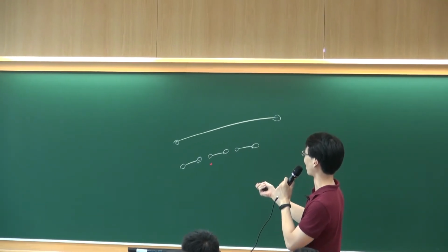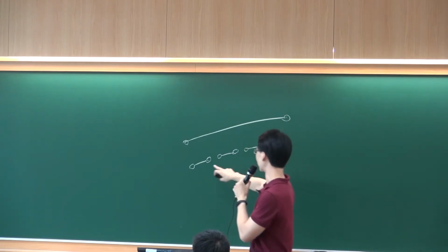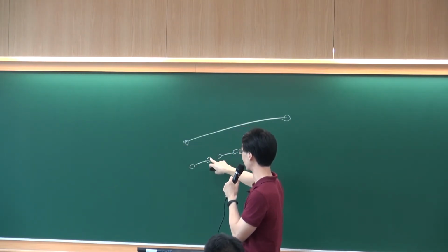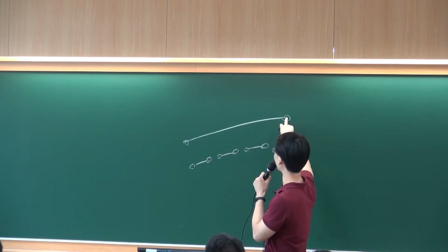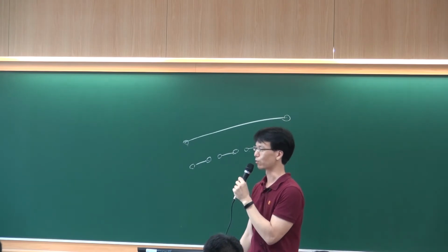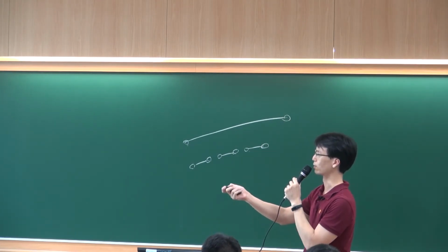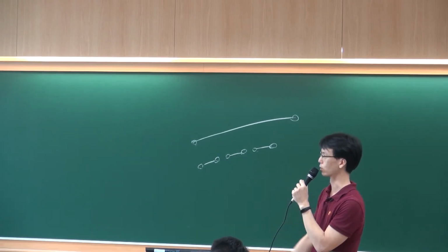Then in this case, I cannot assemble them as a 4-bar linkage, because if I connect this joint, this hole to this joint, this one with this one, but this one cannot reach this one. So that's the very first situation we need to satisfy: this inequality equation.